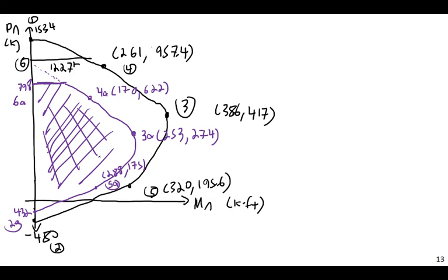Once you have calculated this curve for your column, you do not have a single capacity anymore. I do not have a dirt simple 'here's my moment capacity, here's my axial capacity, check each.' They have to be checked together. The way you do that is you say, I demand that my column carry this axial load and this moment. You go up to your plot and see whether that is inside the factored curve or outside it. If it's inside the curve, you're good. If it's outside the curve, you're not. And that is the basic idea for calculating the capacity of short concrete columns that have moment and axial force interaction. Questions on any of this?